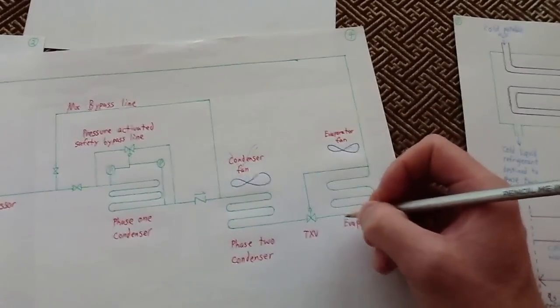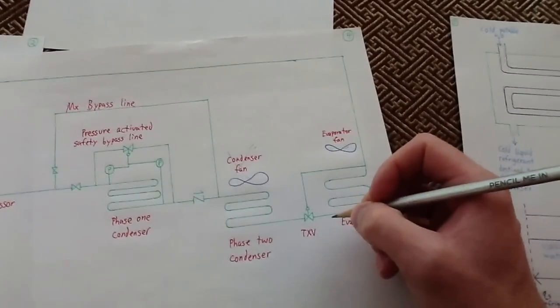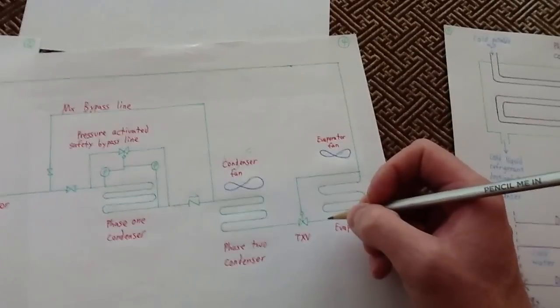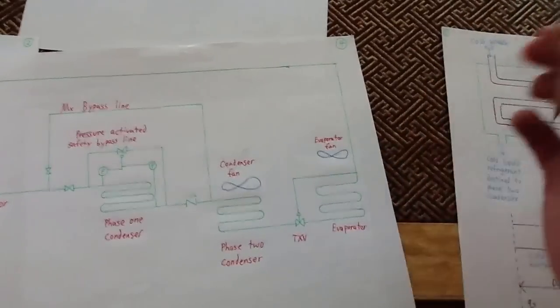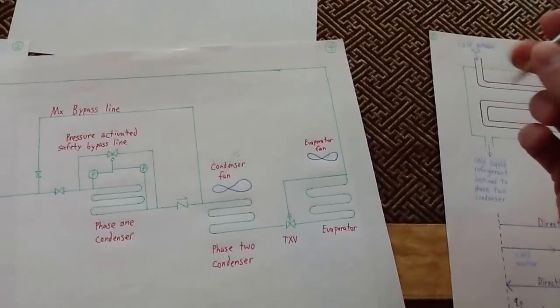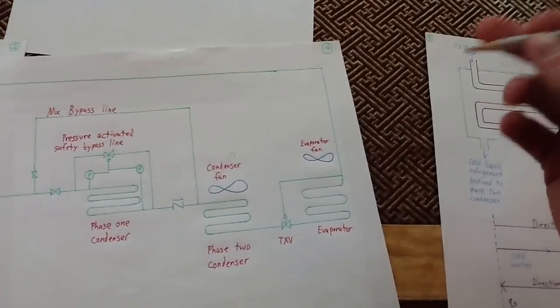You're going to have a fairly subcooled liquid versus a saturated liquid, and because you've subcooled it, you have more sensible heat that can be added to the refrigerant before it reaches its saturation temperature and goes through its latent heat cycle, transferring from a liquid to a gas.